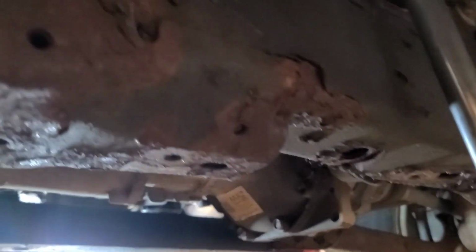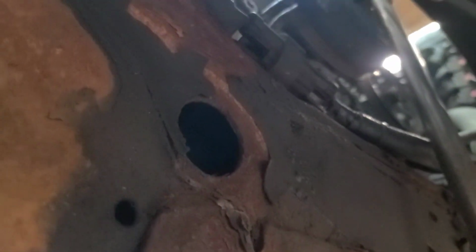Now this is torqued to 59. I torqued it to 110. We backed it off and then torqued this to 59 foot-pounds. Now we've got to turn it 125 degrees. 120 degrees is too flat, so I'm going to mark the bolt up in here so I can see where it is, and mark two flats.